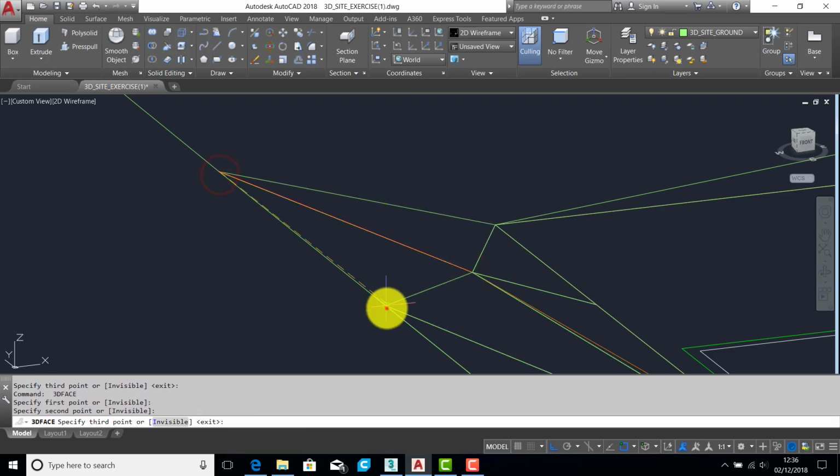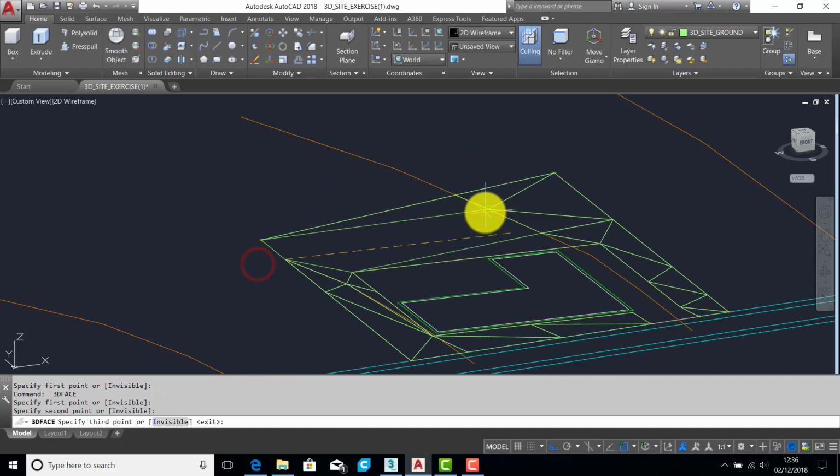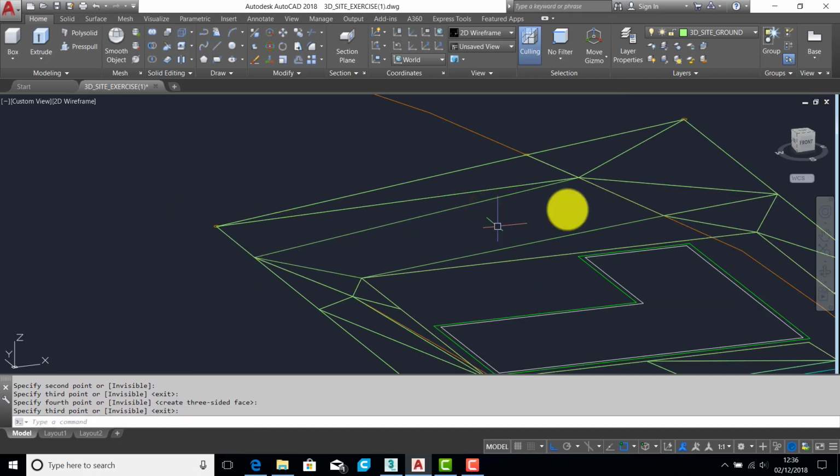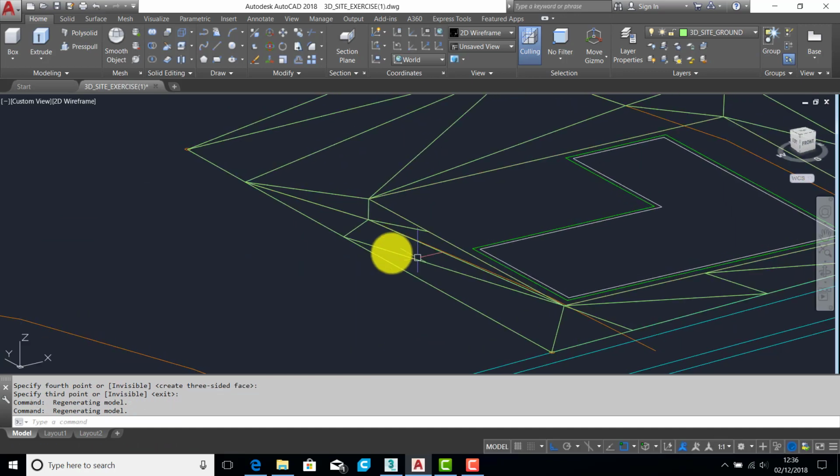Every time you do this, it will be different. I can guarantee you, you'll probably never do the same triangulation twice. It's just the nature of the little task. Okay, we'll put some big triangles here to fill in the last of the space. Now I don't know if you noticed, but I'm drawing the triangles anti-clockwise, and that's so that they're facing upwards. If I drew them clockwise, they'd be facing downwards, which doesn't help the 3D Studio a lot.